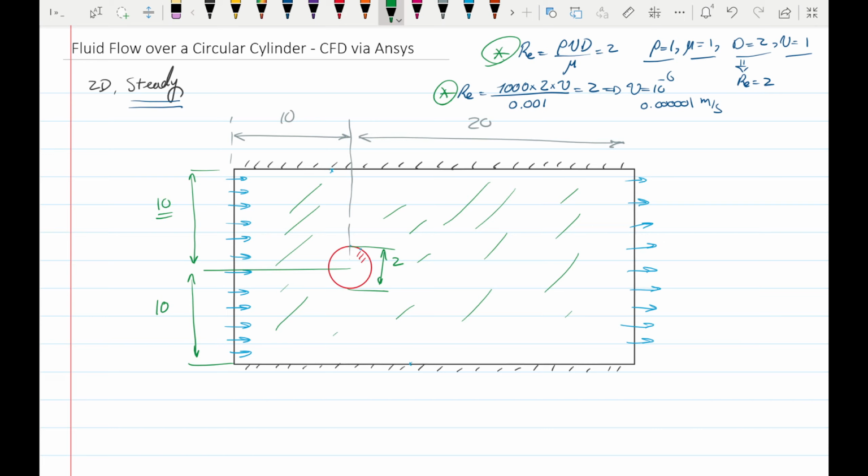So the first is to design the geometry, the CAD part. The second part is to generate mesh, or meshing, or mesh the domain. The third software we're going to work with is the solver, Fluent, which solves the governing equations. The output is a bunch of numbers, and we need the fourth software, the post processor, that gives us the pressure distribution graphs and the streamlines and everything that we can look at, and we can study the fluid flow.